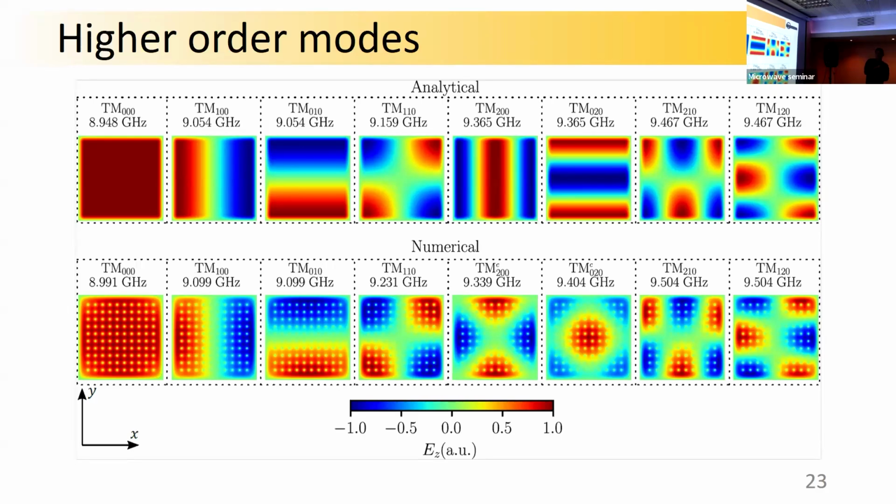But actually, when we are adding that air gap region equal to λ/4, there is a coupling due to these corners that we didn't consider. So the actual field is not with just variation along X, not with just variations along Y, but a linear combination of both. So we have two modes that are different to the ones predicted by the analytics.